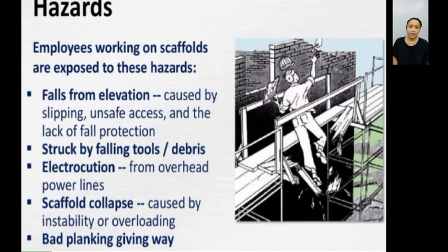Bad planking giving way. This refers to planks that are either unstable, unsecured, or of insufficient size. Planks are the main platform upon which workers walk on the scaffold. If they're unstable, anyone can easily slip and fall off the scaffold.